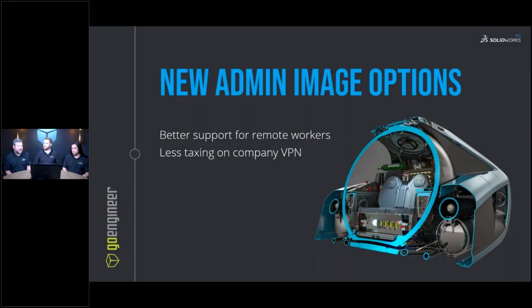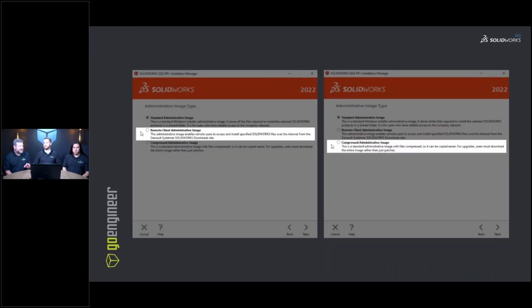This first one, we've got so many people working remote these days. So setting up an admin image for one of those employees, now there are options inside the setup of the admin image to do a remote client admin image. With that, you're really just transferring the setup options across the VPN, and you're downloading the SOLIDWORKS installation files across the internet like you would normally do.